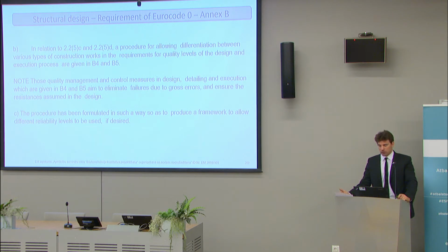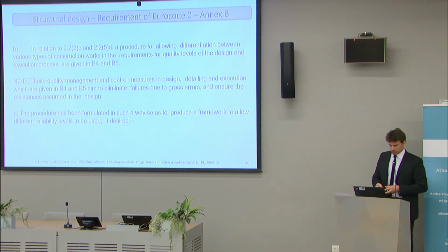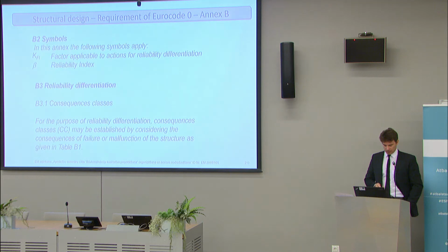What the Eurocode says is that it gives not only the classes of importance and the reliability classes of the structure, but also says you can adapt your parameters a little bit depending on whether the structure is checked by another company or an independent person. So if you have this supervisor, and also if you have more frequent maintenance, and some other parameters that we can see in detail next.